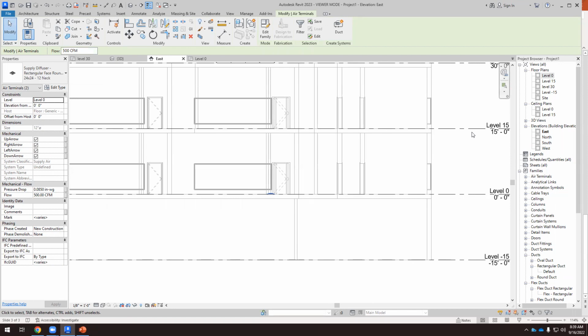Well, we don't have these nice dots with this perforated. So what do we need here? We have a diffuser, and we need a duct like this, the minimum duct, and then the main supply diffuser will be like this. Okay, so that's going to be flex duct. So we need a return diffuser here and flex duct in this direction. And this is the slab.